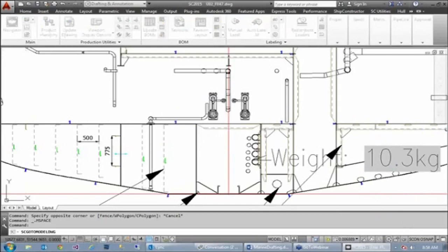What it's going to do now is go to the structure model drawing that part belongs to, which is the frame 47. I'll go ahead and change one of the parts, and I can change the stock as well. Essentially any information that you change here will propagate its way down into the production drawings through our update drawing process that I'll show you here. The auxiliary view.